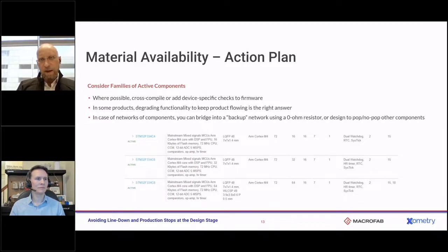One of the other things that we can do here, and I don't do as much electronics design as I used to, but I used to design a number of products. We really can think about our active components and how we use them, especially around things like microcontrollers, considering the family of components. A lot of times you'll find specific models within a particular family have more or less availability than others, but they may differ in the amount of memory, or in a function you're not even using. So you can pull from that family where possible.